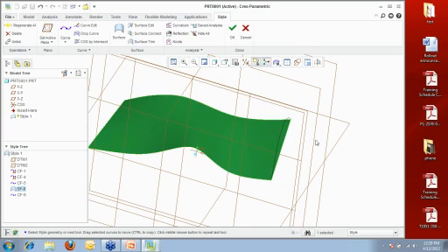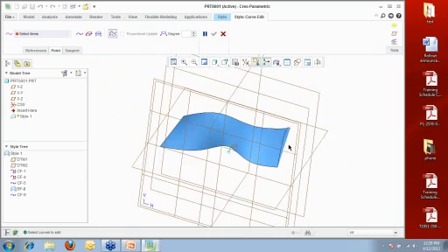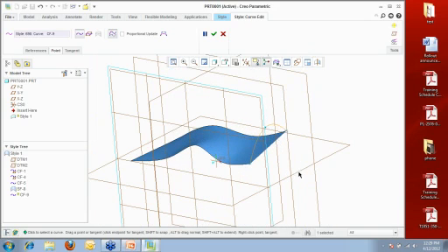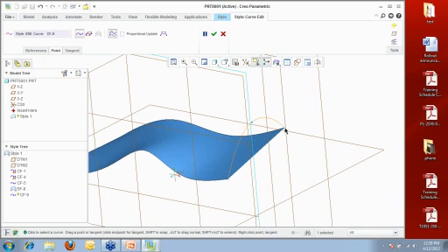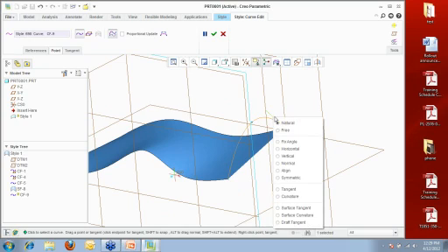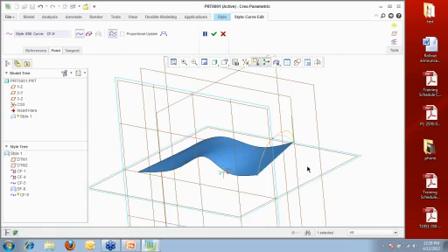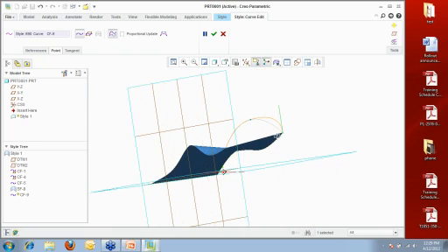Anyway, regarding the adding of curves and the idea behind manipulating curves, one thing that you have here, if I come into my curve edit function and pick my curve, is where editing of curves also becomes very unique. Let's say that I wanted this curve to be normal to this surface right here. You have the ability to control end condition by picking on the ends and then right-clicking on these drag handles. And this is what makes this really unique compared to just creating curves through points. I can say I want it normal, and it asks normal to what? I want it normal to that surface, or that plane right there.